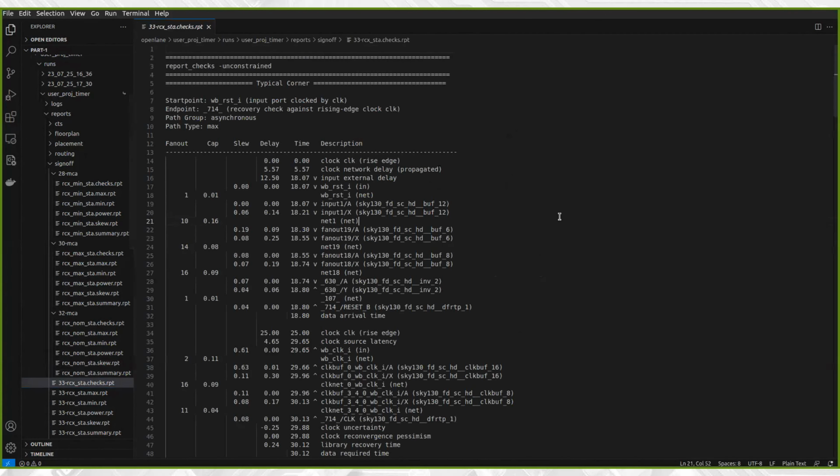Let's start by verifying the STA inputs. They include the timing constraints, or SDC file, the design and sub-macro files, gate level netlist, and parasitic extraction file SPEF, or timing models, and the technology libraries. All inputs are handled by the flow except for the SDC, which is the base SDC provided in the configuration.